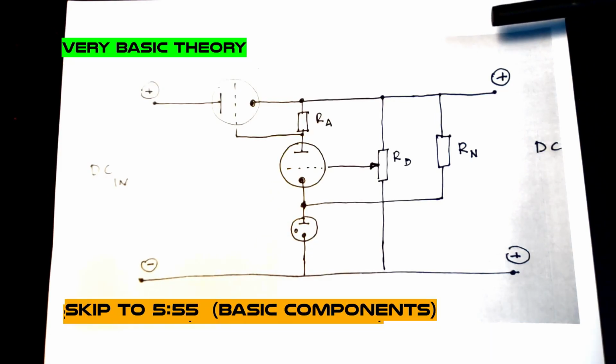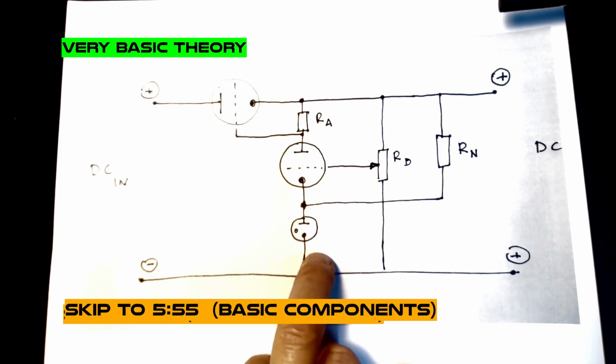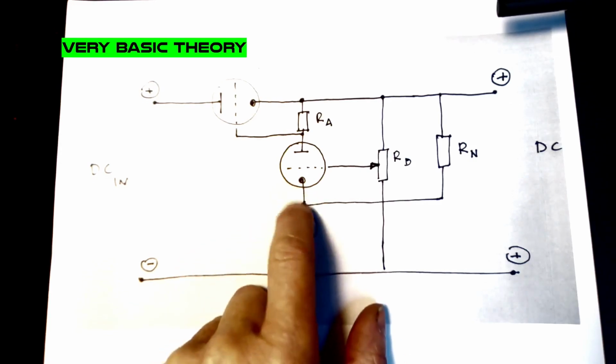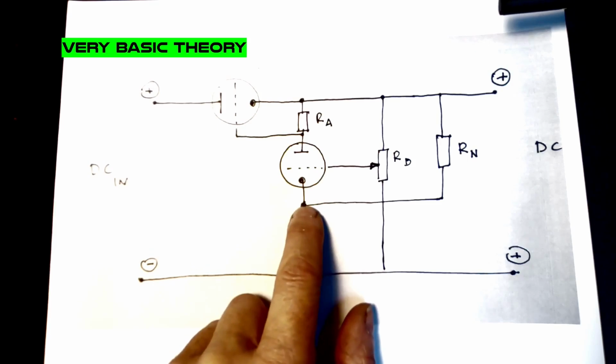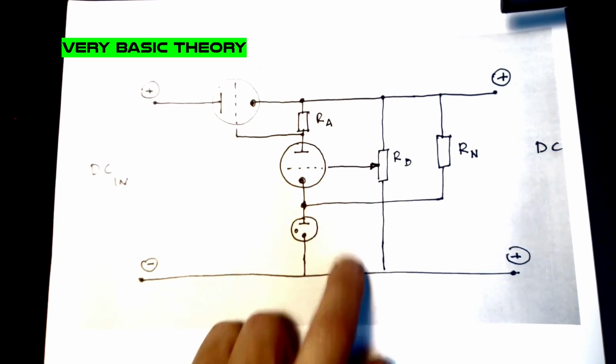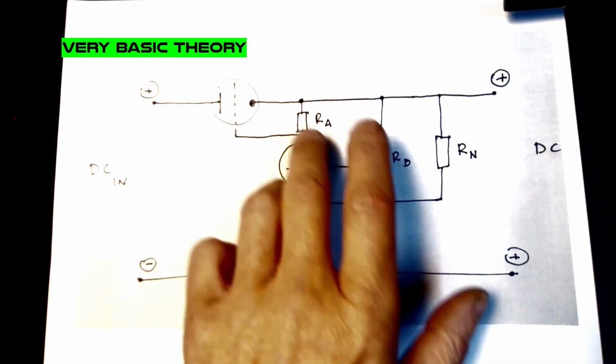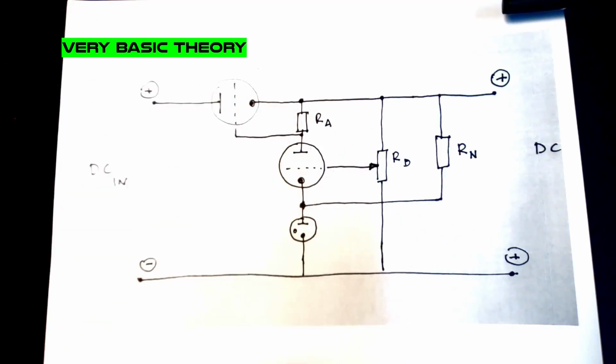The voltage reference element holds the cathode of the error amplifier at a certain voltage above ground. Let's say the output voltage rises because of a change in load.